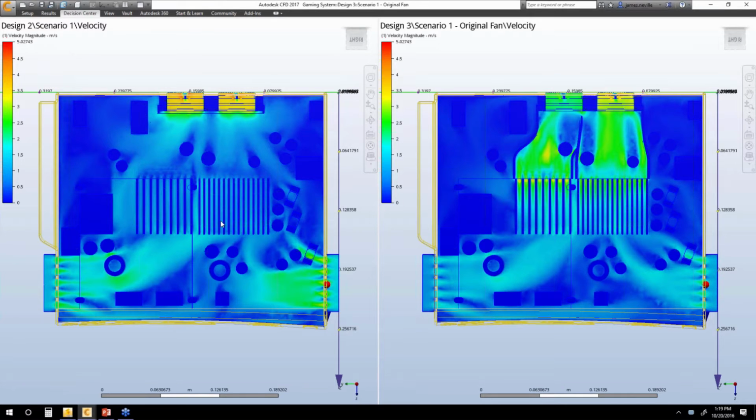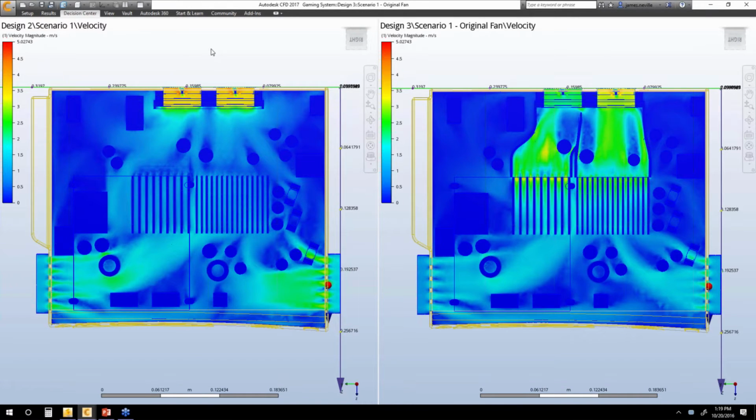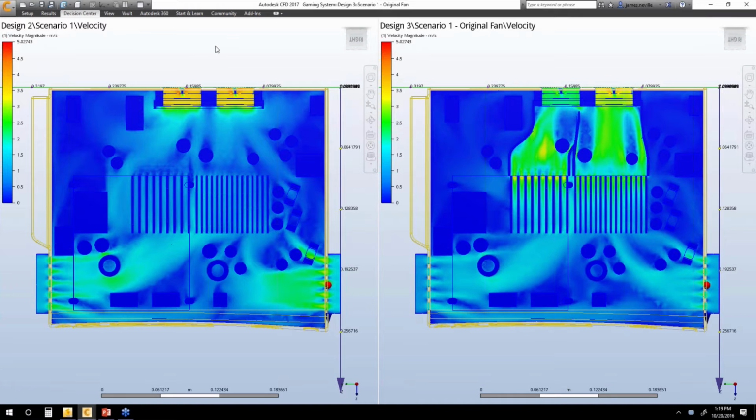So what I've done with design 3 is the vents are in the same location, but if you look on the right, there is a shroud in place. So there is a sort of a focusing shroud on the back end of the heat sink. You can sort of see the outline here. Maybe I'll do, I've got a couple better images here in 3D that'll better illustrate this. But in effect, what this does is it focuses all of the flow that's being pulled from those fans. All that flow must come from the heat sink. So literally, these are like guides that are keeping all of the flow through the heat sink, and you can dramatically see a difference here.